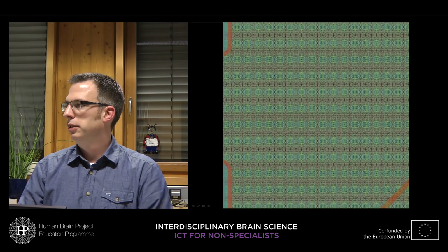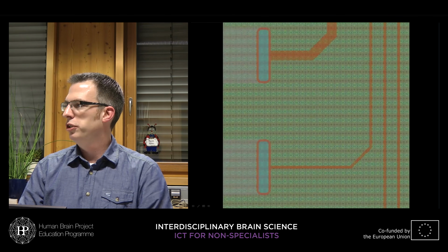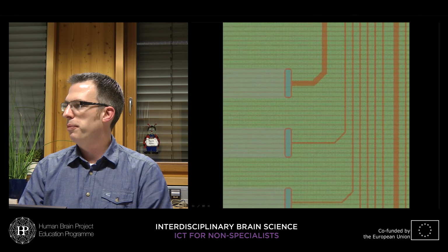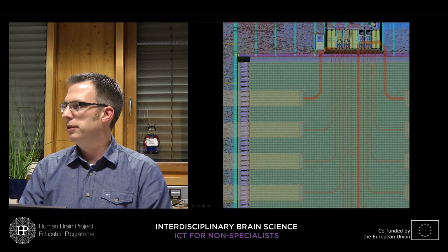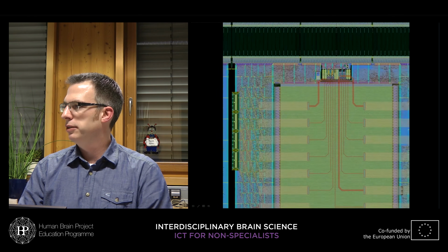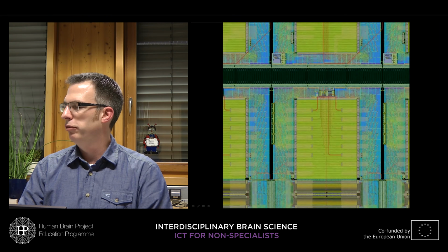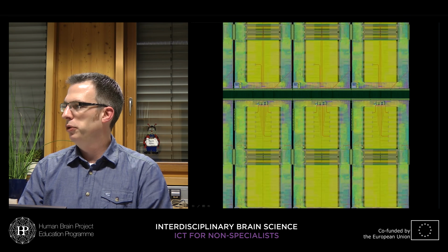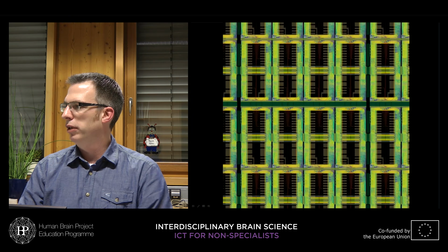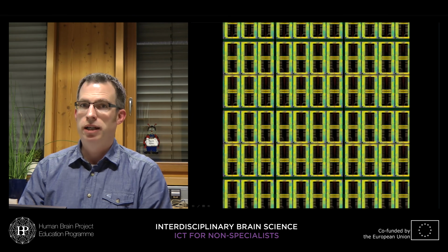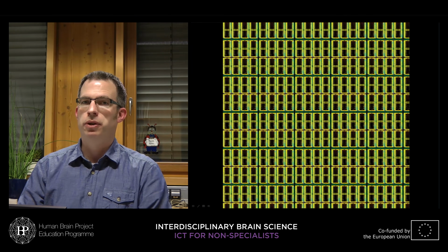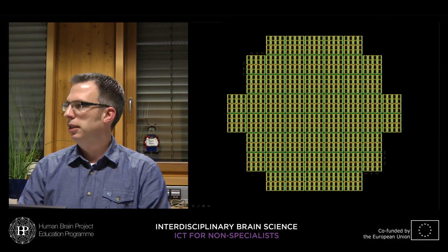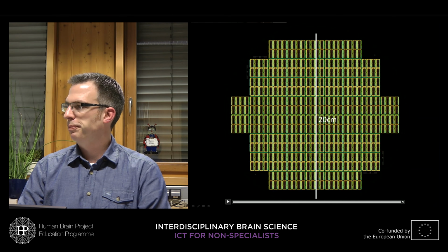And there are, in one of the homogeneous areas, more than 50,000 synapses. You can now see the structure of the chip, the neurons coming in from the bottom. Now you can recognize the layout of our HICANN chip, and there are many HICANN chips on one so-called wafer. And now we are done.